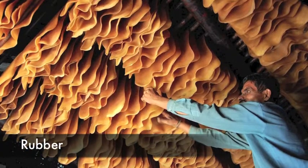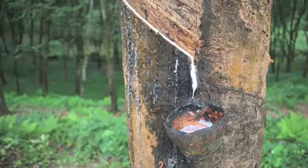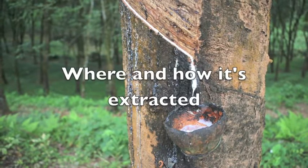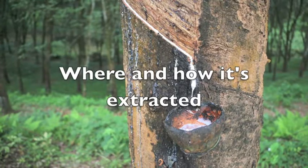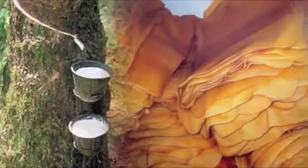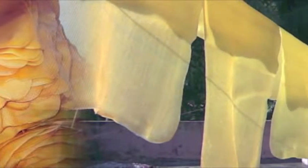My next material is rubber. 80% of natural rubber is grown in Thailand, Indonesia, and Malaysia. Rubber is taken from rubber trees, while latex is collected by making a cut and letting it drip into a bucket, so it's found in a liquid state in nature. It gets filtered, then formic acid is added for coagulation. That makes it a hard rubber instead of liquid.